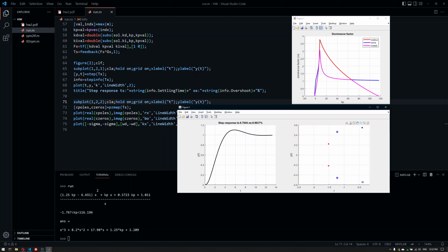It is roughly 0.4, and 3 times 0.4 gives us 1.2 as far as I remember. It would of course be working better if we had 4 or 5 times dominance, but that's not possible with a PID controller with these specifications for this specific system. But we can examine the system in terms of dominance factor, because that is all that matters for dominant pole assignments.